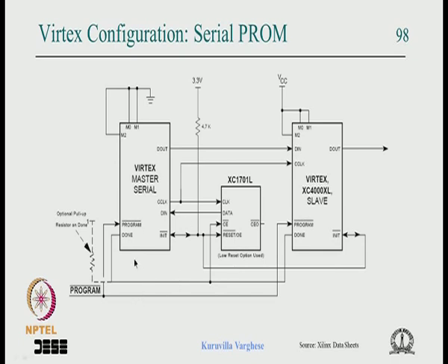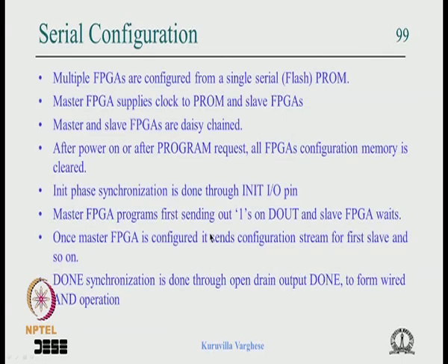Normally an SPI flash will be connected in this fashion to the FPGA, so that you can program this flash through a JTAG port, and if you put appropriate mode pins, the FPGA can be configured from the flash PROM. All that is possible, and that is what is written here.